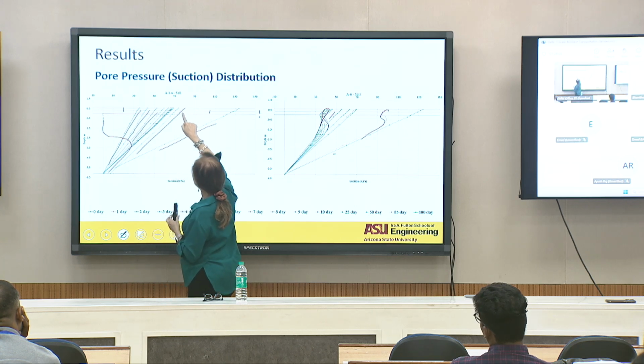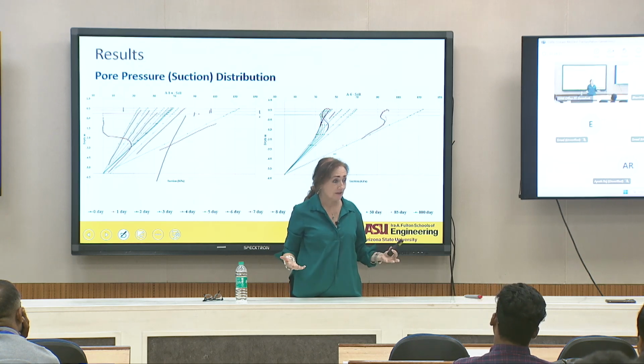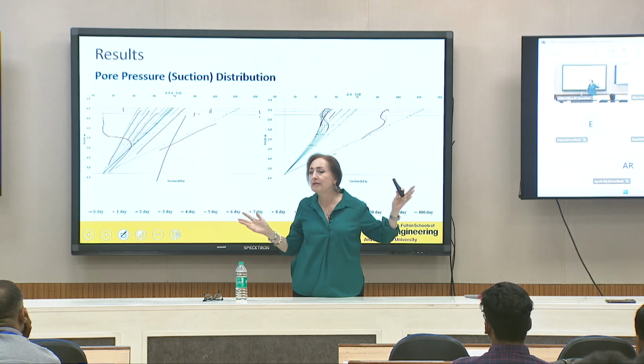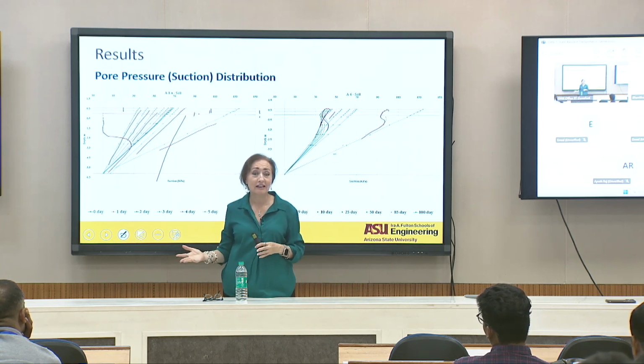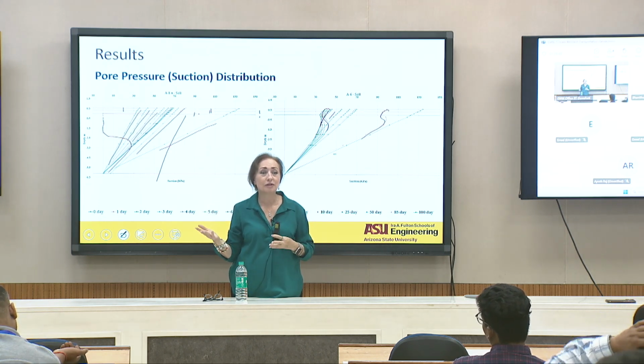But when you jump to the next layer, you might have some water content in here, and you jump to the next layer, you're going to have a different moisture content in here. It's not a continuity between moisture contents, right? Because you do have different materials. So they might be all saturated, and you're going to see the granular base is saturated at 15%, right? And the subgrade material might be saturated at 35%, right? So you do have the same degree of saturation, but you do have different moisture contents.